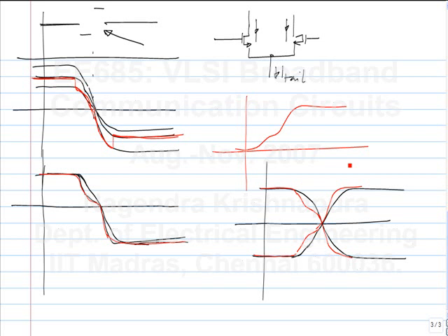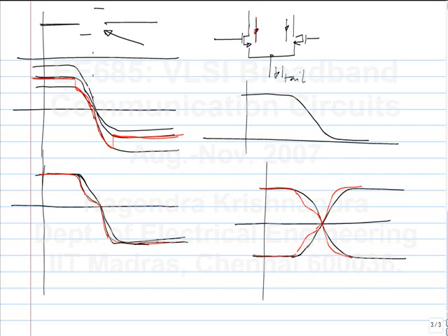If you look at each of these currents, for the ideal case, they will look like this. And for the non-ideal case, here the current is smaller, and here it is larger and it does something, and here it is smaller and larger and does something of the sort. So the falling transition is different from the rising transition, isn't it? If you look at each of the single-ended currents, a 1 to 0 transition will look like this, and a 0 to 1 transition will look like this. But they should look opposite of each other if it's a linear case. So the single-ended waveforms are non-linear.